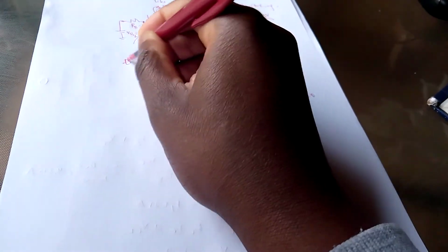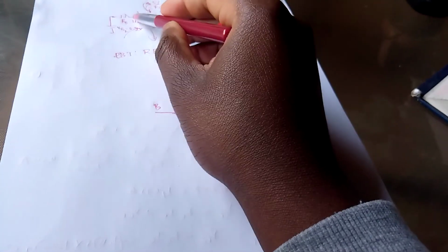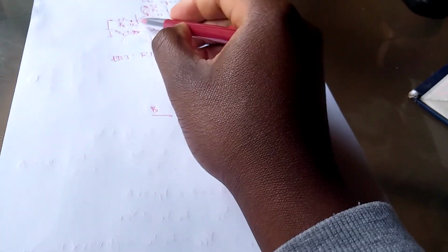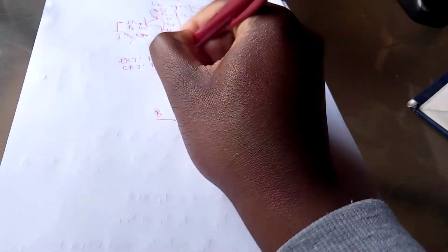It was just of interest to go back onto them. So there is an intermediate mode. And by the way, before we carry on, in the cutoff region, the EBJ junction is reverse biased, and as we've demonstrated, that's because the voltage on the base side is not higher than the barrier voltage of the diode between the base and the emitter, and the CBJ junction is also reverse biased. That's what makes both junctions reverse biased, and we know we are in cutoff mode. The transistor operates like an open switch, very important.